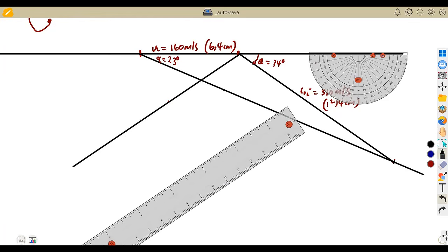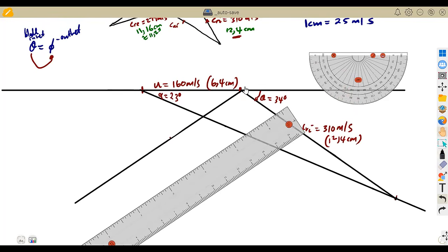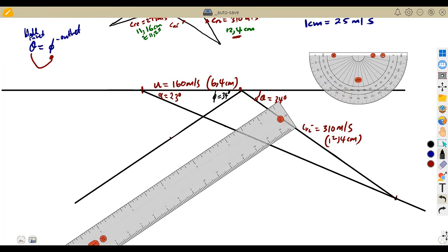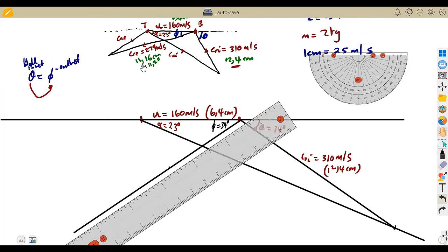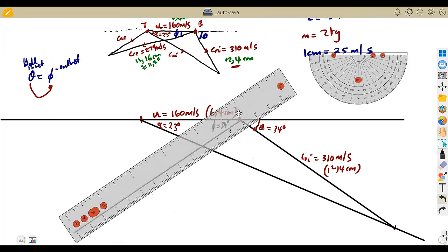And since we measured the angle, remember this line was at an angle of 34. We are talking about the exit of the blade here, which is 34, which is outlet, right? But we also have the distance, so you can even mark here, because we're given that it's 11,2 approximately. It was 11,16, but just measure 11,2 along this line.